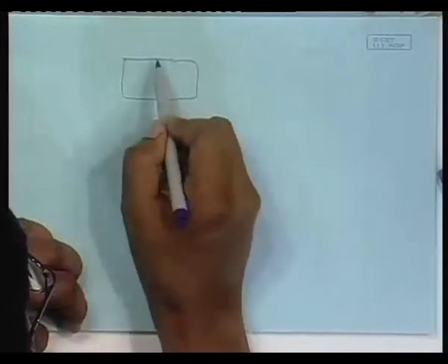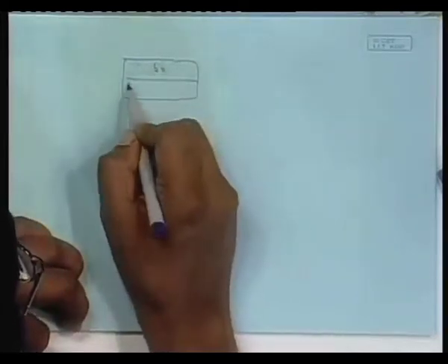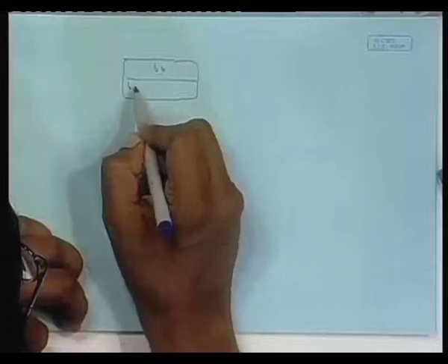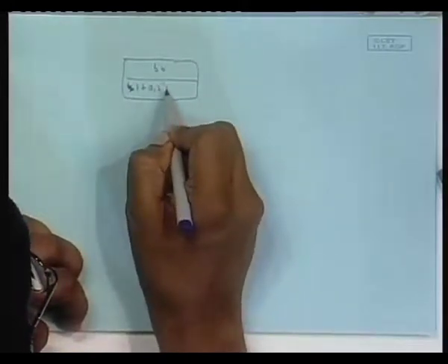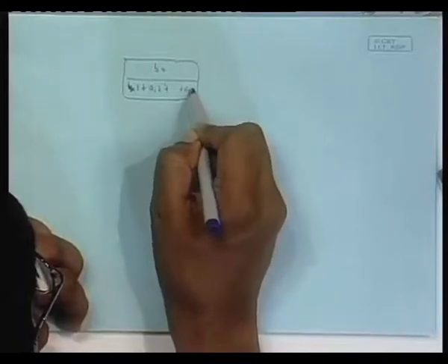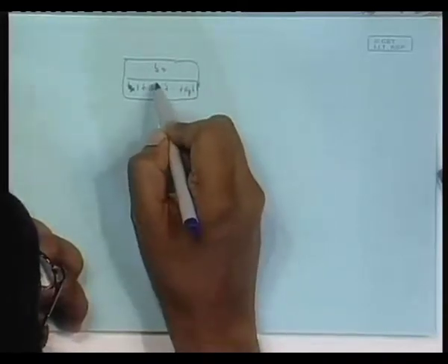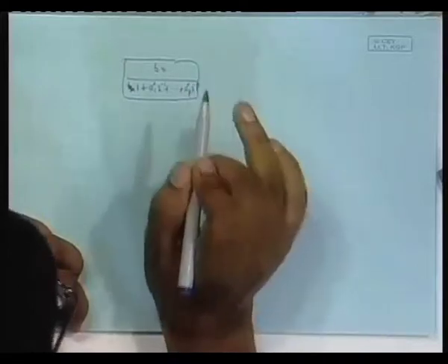The one which has really been a great success is the autoregressive modeling, the AR model. In the AR model you have an all-pole model. The numerator coefficient can be B0 like this. Sorry, this is 1. Instead of A1 to AP, let me call them A1 prime to AP prime for some reason.